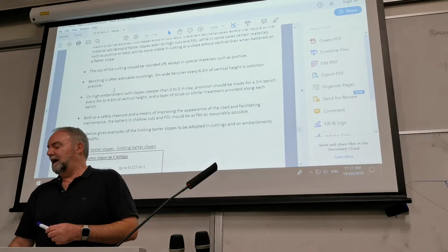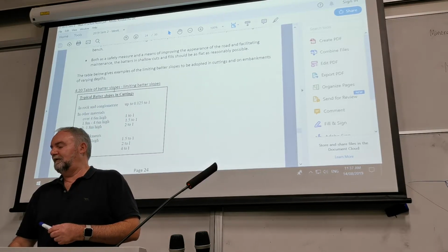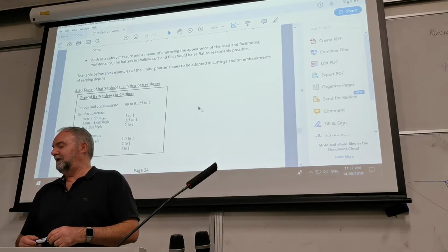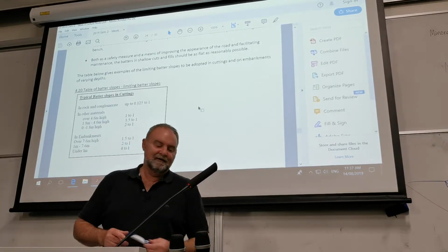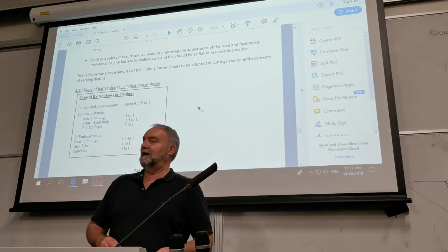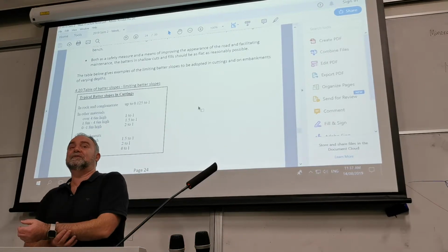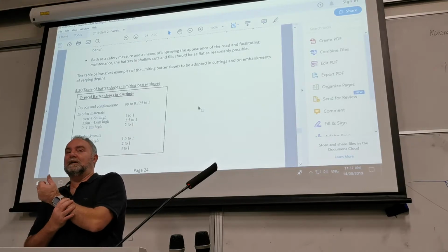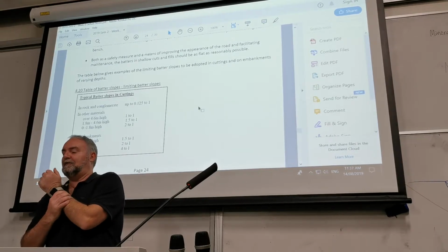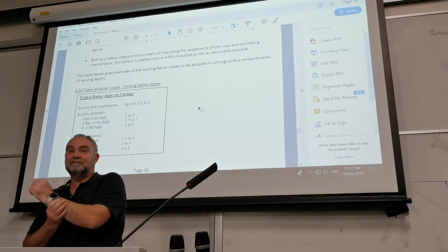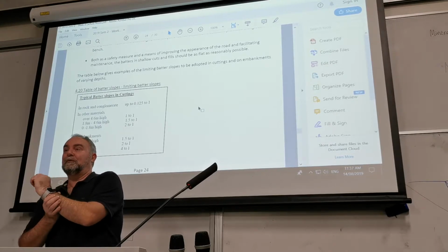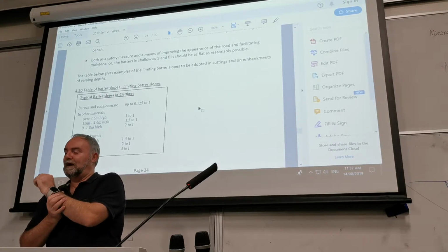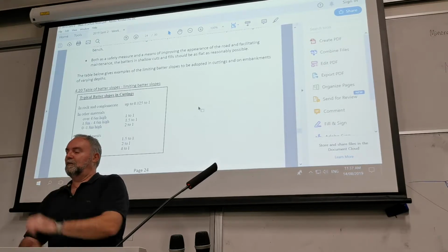There are some typical cut and fill batters as well. Now we're going to keep talking about my geotechnical engineer next week when it comes to volumes, because that also affected our volume calculations. Anyone that's done any geotechnical engineering will know that every soil has a different compaction factor, and we'll talk about the compaction factors and relate that also to working out our volumes.